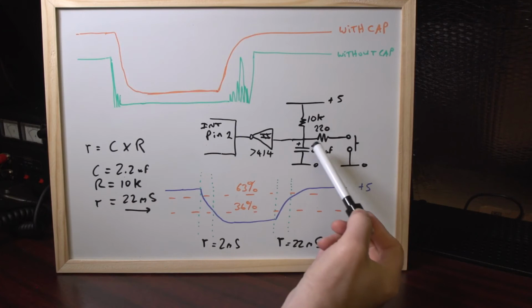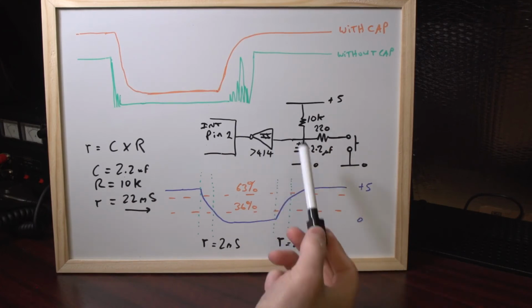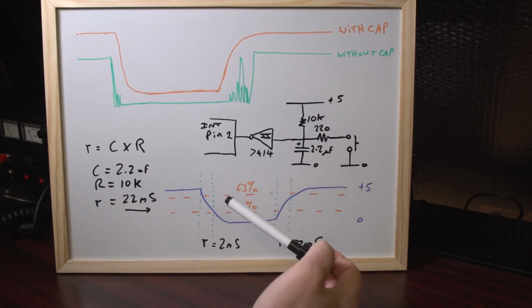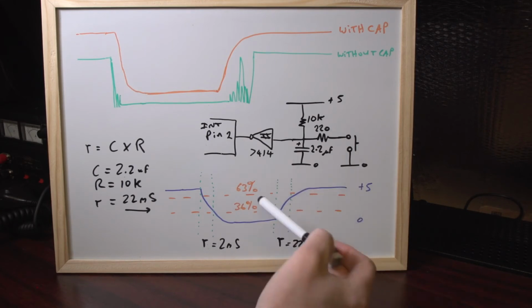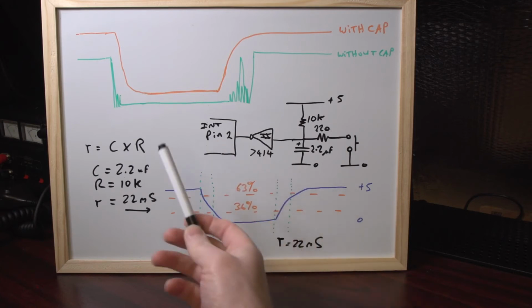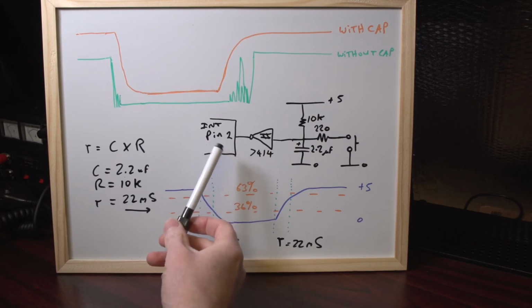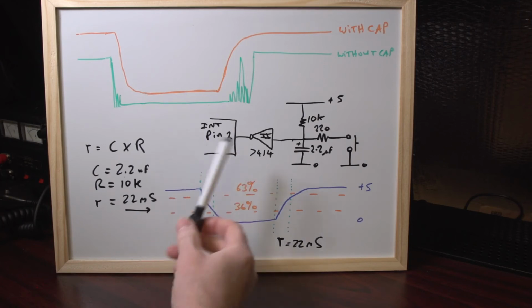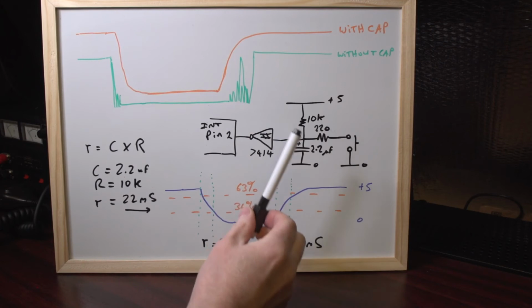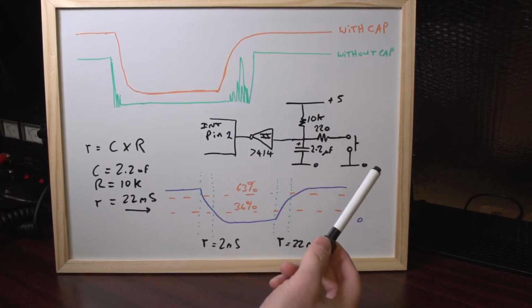If we just had this capacitor coming out here, that's going to be way slower than 9 microseconds per volt. Anyway, I'm not going to go too far into this. It's probably a subject on a forum that needs to be discussed with other people to see what they think. But it could actually be a design fault within the ATMega328p chip and possibly other chips of that series. The rise time must be faster than around 9 microseconds per volt.